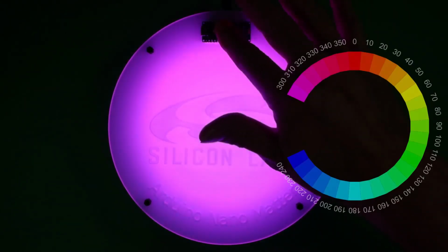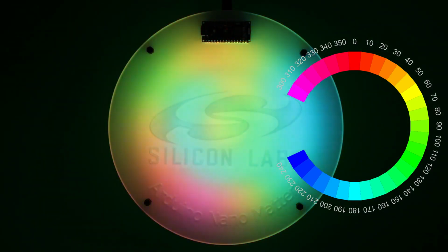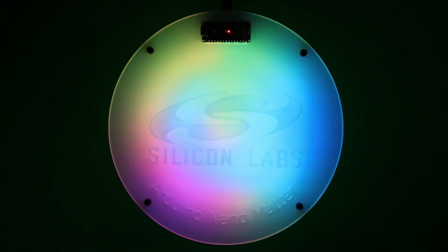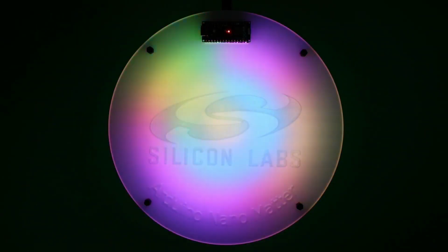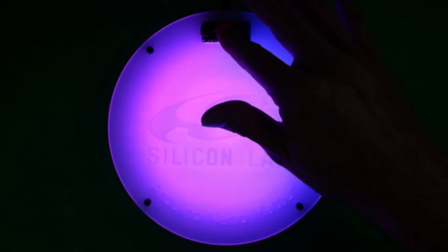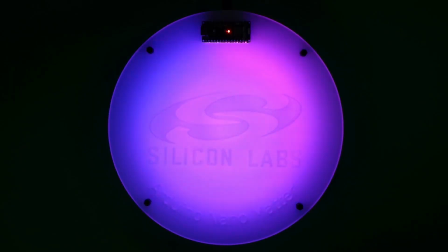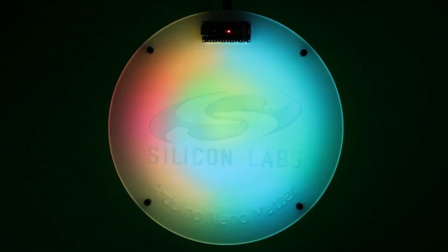Pressing the button again moves us on to the more pronounced gradient that takes the long path around the colour wheel. The animation is achieved by moving the slice up and down within the noise image, and at the top or bottom moving 1 pixel left or right. To reduce repetition, the image width and height are prime numbers. The third mood light mode returns to the short gradient, but this time bounces the slice at a 45-degree angle around the edges of the noise image to generate more movement. The final mood light mode keeps the 45-degree movement but swaps back to using the long gradient for the most pronounced animation effect.